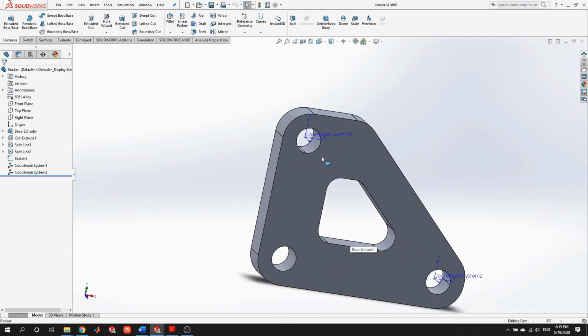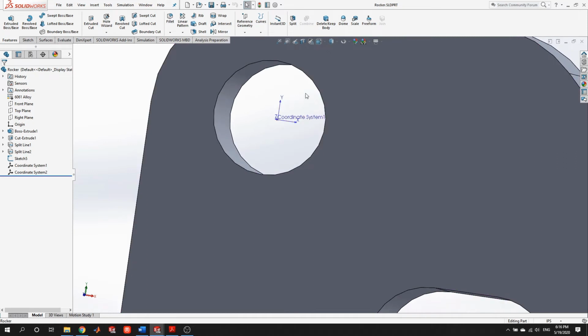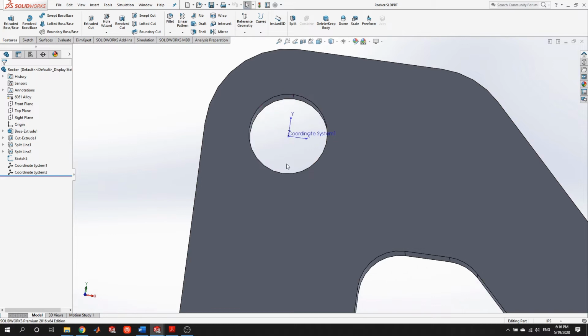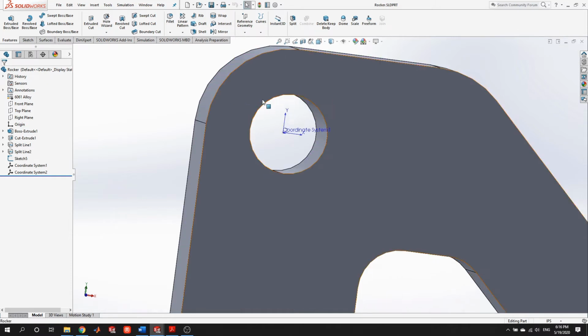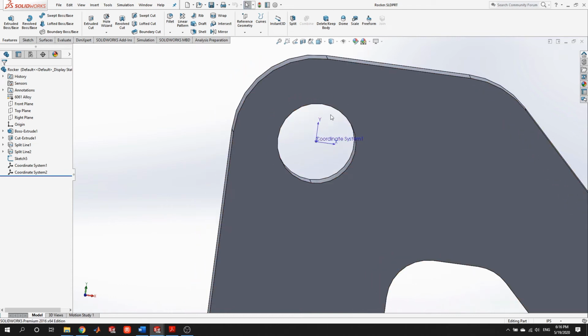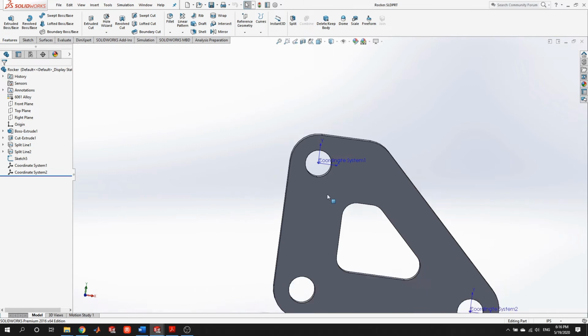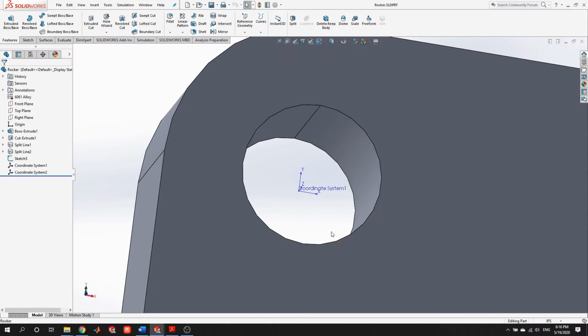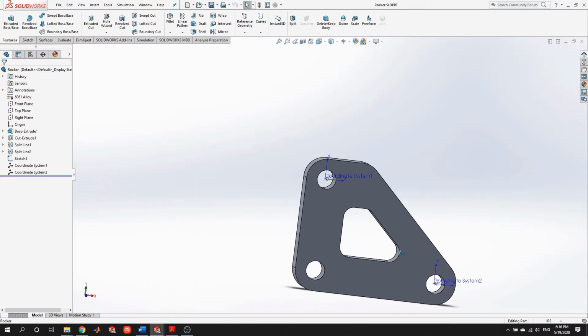And this can be a technique that you use because if we were putting a restraint or some sort of load and we are grabbing the entire inner face, this would almost be like we're pulling in different directions. So you do have to be careful. For example, if we were to grab this inner face and then even tell it to have the correct direction, on this side, it would be pushing, just like we'd expect, but on this side it would almost be pulling, as if the axle was bonded onto the inside face. So by making the split line feature here, we can really just load up part of the face and give a more realistic boundary condition.